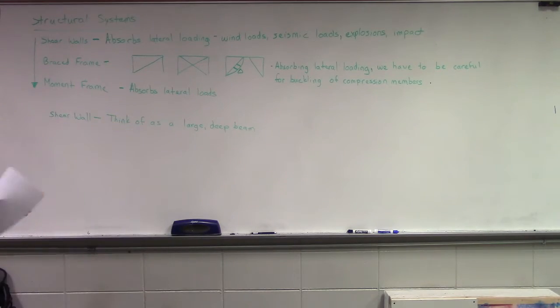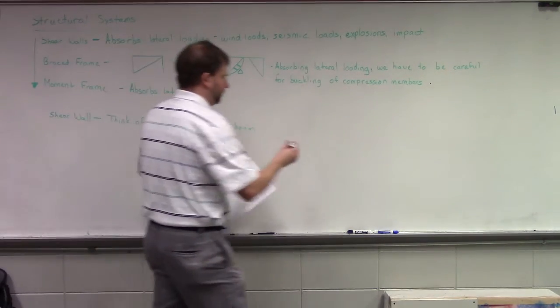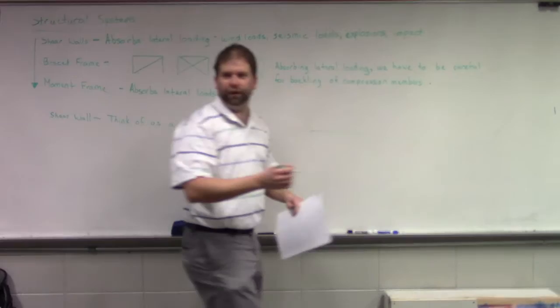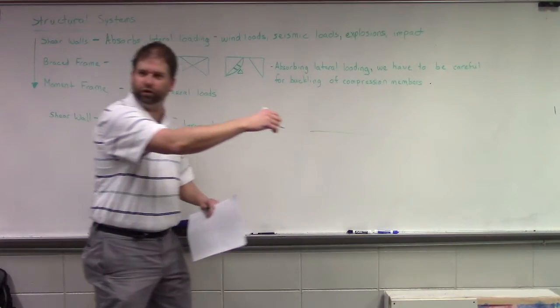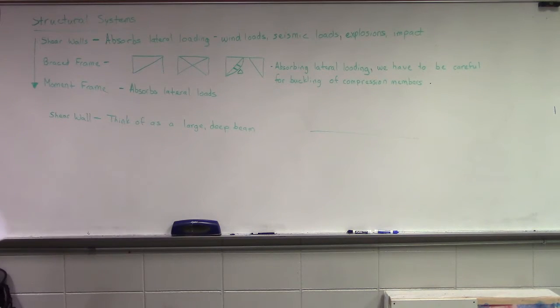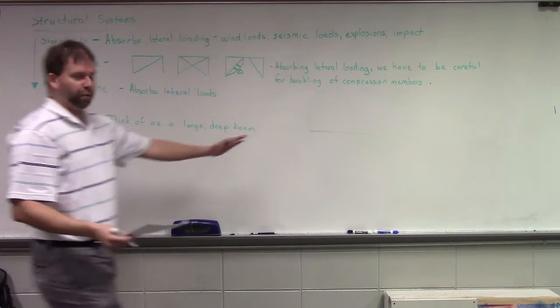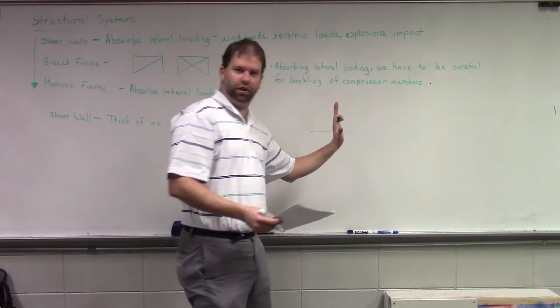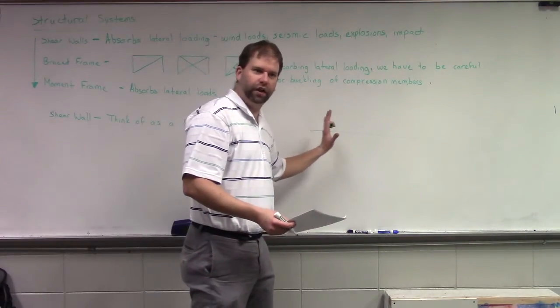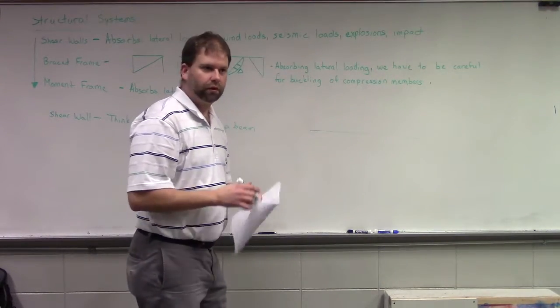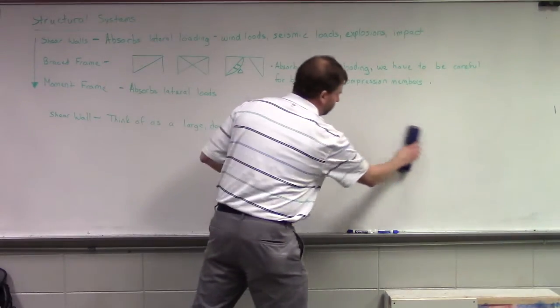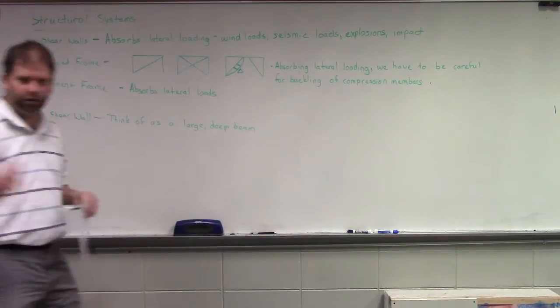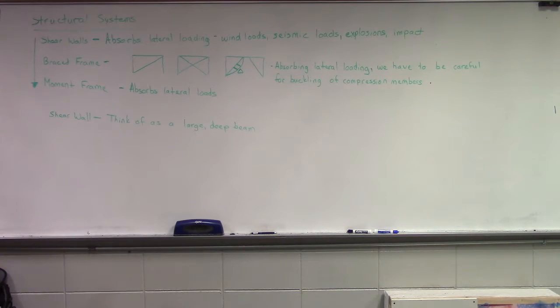And so now we can take it, instead of it being this goofy line that I draw up on the board over and over and over, and I pin it on one side and put a roller support, couldn't we do that with our shear wall? Tip it up on its side and give it dimension into and out of the board and analyze it in the same way? Yeah. Okay? So that's what we've been setting up for, is to take this simple analysis that we've been doing all semester and start applying it to these 3D structures.